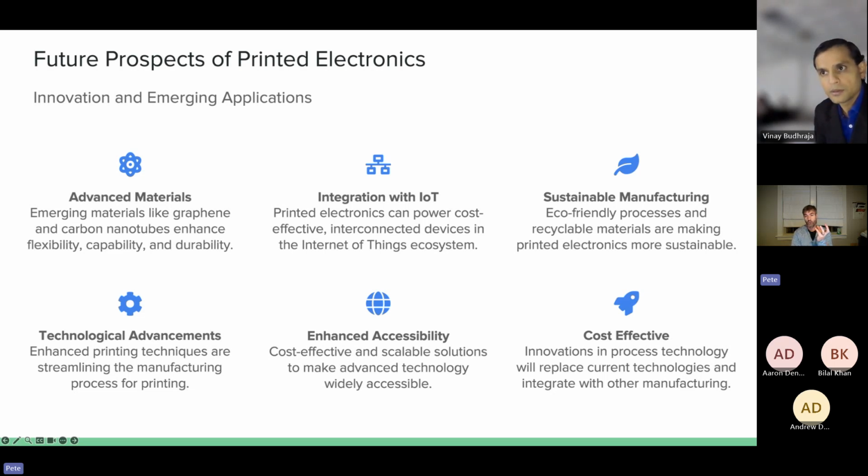So we're more writing and pumping. The advantages of this are we're able to print higher viscosity materials, upwards of 450 centipoise in viscosity. We don't require specific tuning to our printer, whereas most inkjets require specific tuning.